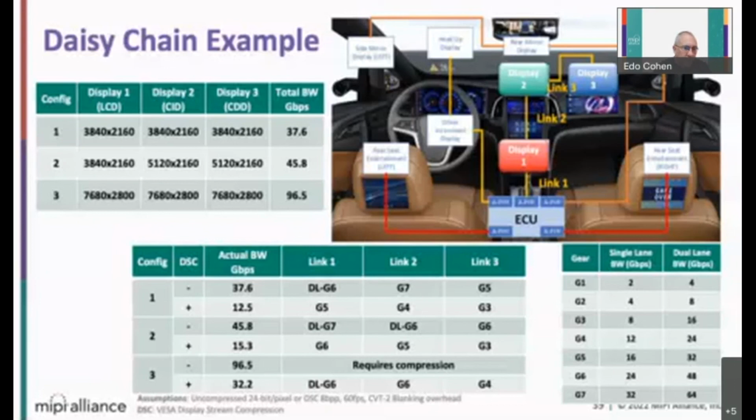So that's a very unique and strong capability, and I think it is very important to understand that for A-PHY, due to the very low packet error rate, it is possible to apply the compression without any unnecessary overhead to the net data rate.